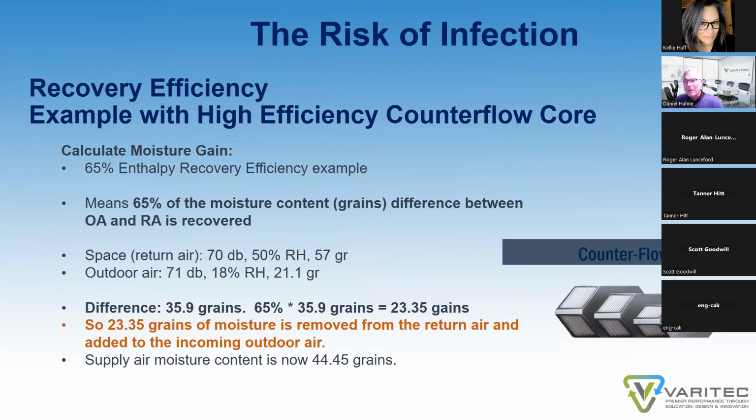We know about enthalpy wheels and heat recovery for dehumidifying outdoor air during our summer monsoon conditions. Very effective at that. But if we reverse the process and apply it during our driest times of the year, you can have significant grains of moisture reintroduced back into your outside air stream and redelivered to your building if it's properly designed within a unit.